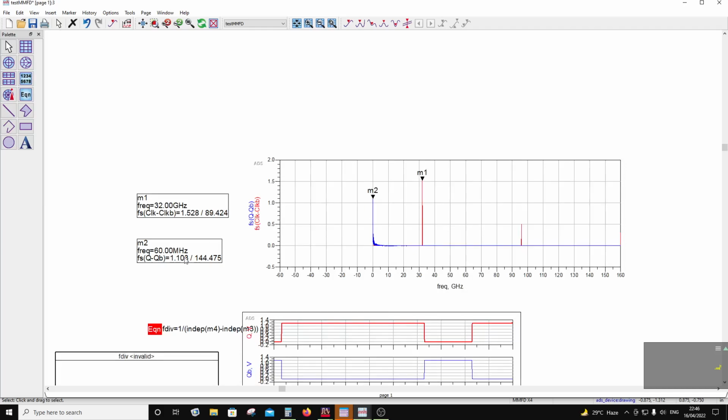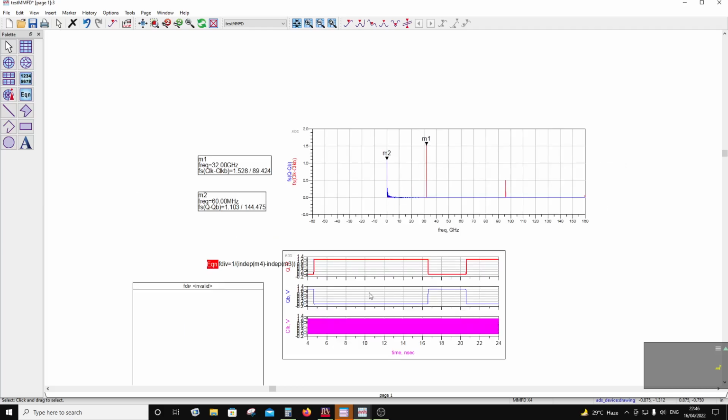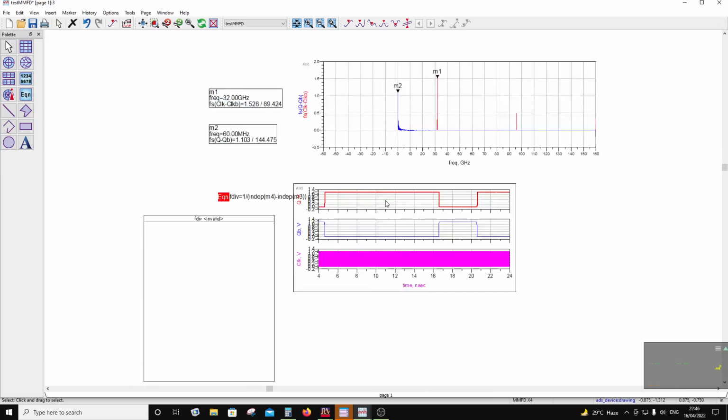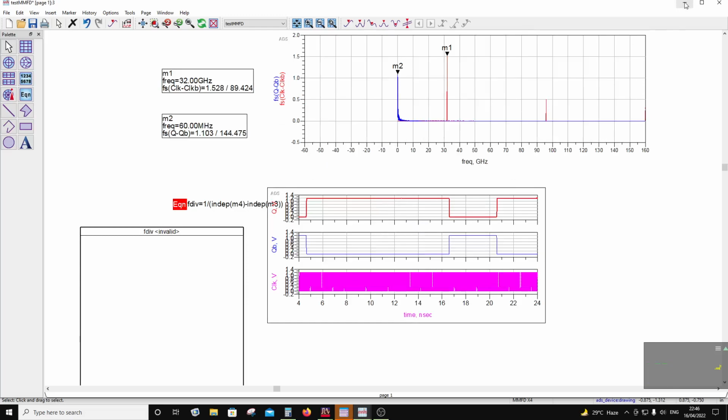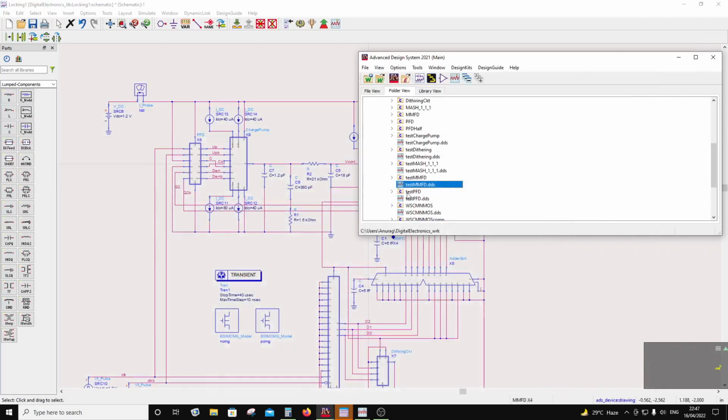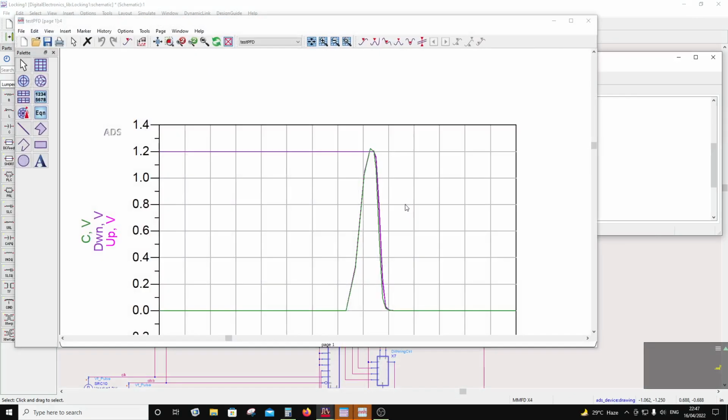Now here, the way to do it is I just compute the time period by putting 2 markers, and then you can look at the frequency plot also to see whether it is that ratio. Anyways, this is a multimodulus divider which is doing the divide. Okay, now once you have done the divide, you go into the PFD, and this is the PFD. So I'm just zooming in.